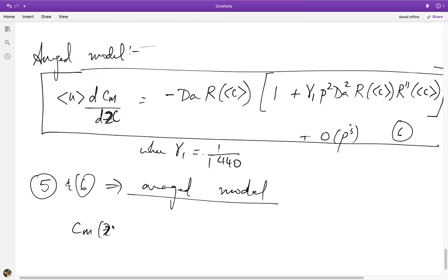So the cup mixing average at X equal to 0 is simply the cup mixing definition applied to the inlet concentration. This is strictly true if the inlet concentration is uniform across the cross section. If not, there are some corrections in the form of initial condition, which can also be derived by some refinements to this averaging procedure, but we shan't do that in this lecture right now. But it can be done. But if you have a uniform well mixed inlet solution entering which has no radial variations at the inlet, then this is exactly right.